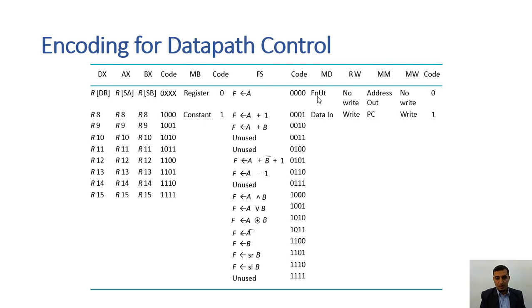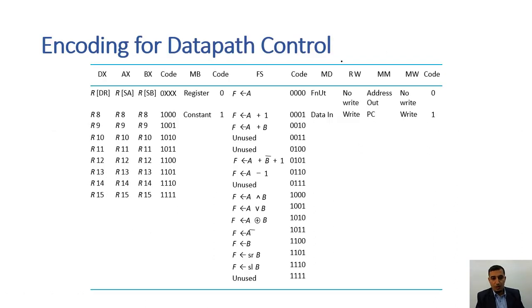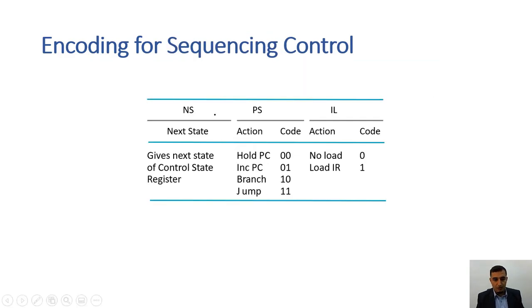Today we are going to take examples and talk about the multiple cycle instruction computer. We stopped last time when we talked about the encoding of the data path signals. These are the signals that we are used to. This is the extra part for temporary registers. Here we have the encoding for the next state, which we said we can have 16 states.